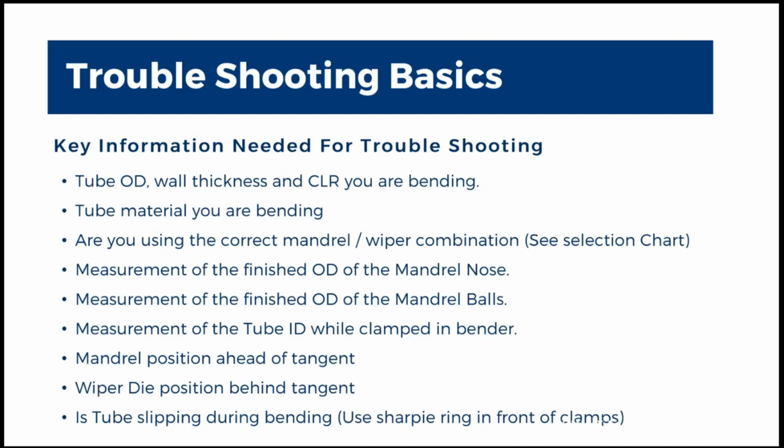Measurement of the finished OD of the mandrel nose, measurement of the finished OD of your mandrel balls, measurement of the tube ID while clamped in the bender, mandrel position ahead of tangent, wiper position behind tangent.